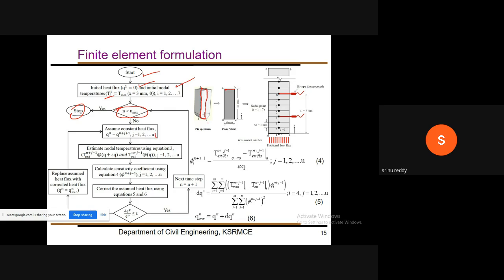And in the initial step, if you see here, assume the heat flux constant. The frictional heat flux, we don't know. We have not measured anything, and how much the actual heat flux is at the contact position, we don't know exactly. We have to assume some dummy value here. That dummy value I have assumed increases from 1. So I have started with heat flux value 1, and suppose at the first second I assume the heat flux, which I represent with Q, is equal to 1.